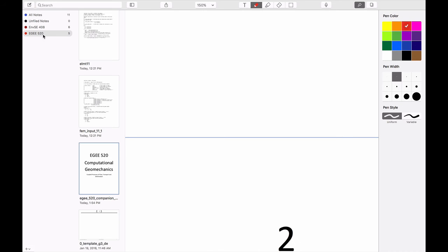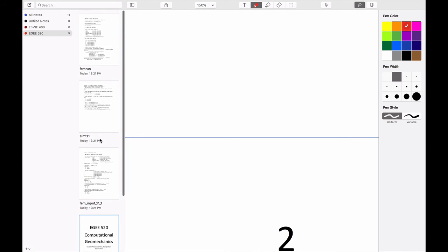There are slightly more sophisticated ways of doing that as well. Obviously, if you use this method, you'd have to compile all of these. If you had 10 elements, you'd have to do this K-stiffness thing 10 times and add it in 10 times. And so that's not quite the way that finite element codes work in a mechanistic way.